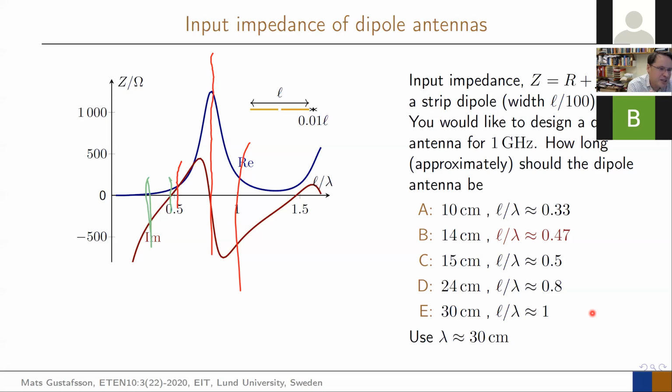There is nothing that says that half wavelength dipoles are perfect. They are a really good thing, but they are not really half a wavelength. They are slightly off from it. And that is something that we, of course, need to know in these cases. Okay, we will continue with resonance after the break. I'm sorry I drew over a few minutes, so I will stop here.